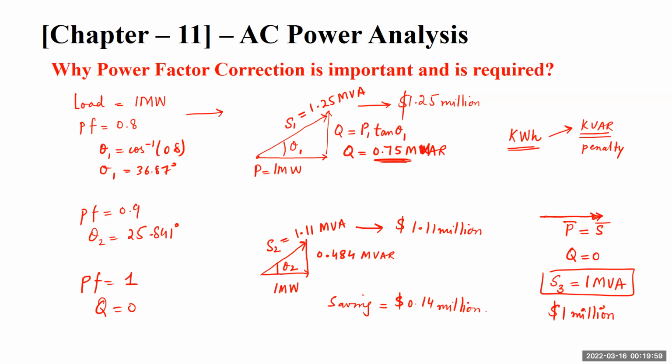that is introduced on those industrial units. And the reason for poor power factor in these industrial units is these pumps and induction motors and these sort of components, which have big windings attached to them, or a dominant inductive component, and that is because of the inherent nature of those devices.